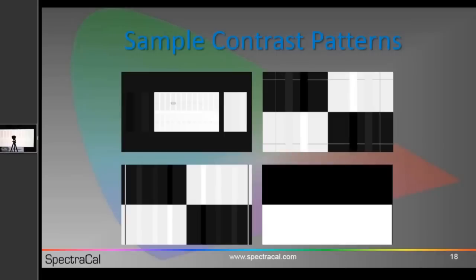And we would do the same thing with any one of the other test patterns from other test pattern sources, where again the common theme there is that we have a bright white portion of the test pattern with other bright gray sections on that, and we want to set the contrast control as high as we can without losing that bright gray detail, not blending it into the background.